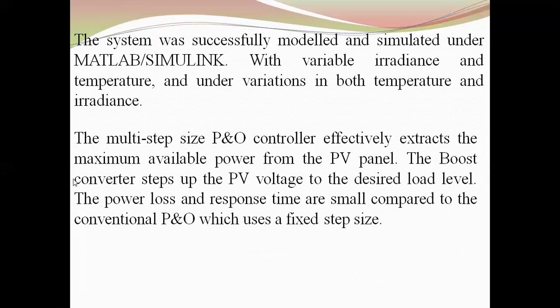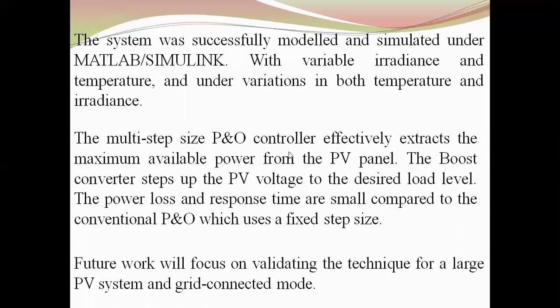effectively extracts the maximum available power from the PV panel. The boost converter steps up the PV voltage to the desired load level. The power loss and the response time are small compared to the conventional P&O, which uses a fixed step size. Future work will focus on validating the proposed technique for a large PV system and grid-connected mode.